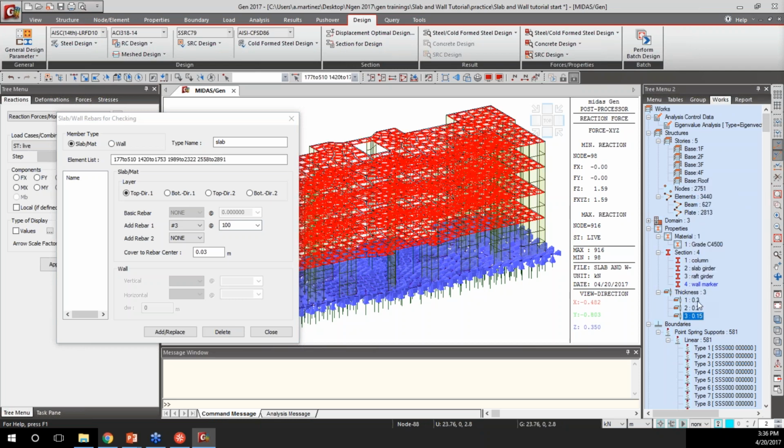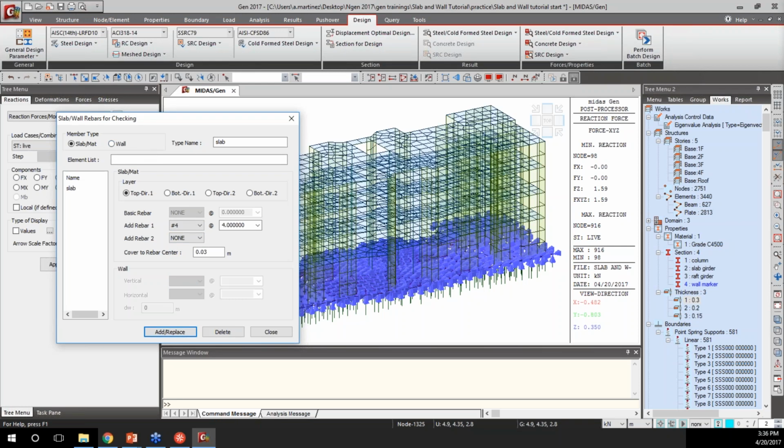Select the slabs, and if you right click, you have this other option that says select plus, basically just add on to whatever you had selected. So we're specifying specifically the rebars, and we would do the same for the wall. So these being millimeters, and we select here.